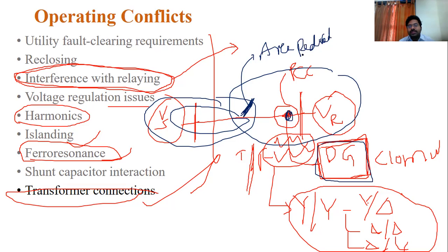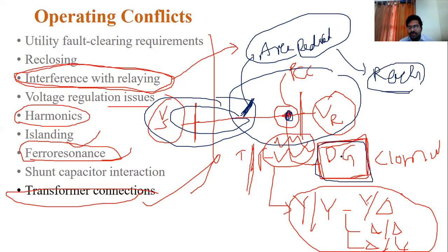Then you call the reduction in that area the reach. Reach of the relay is reduced because of adding this relay to this one. Okay, so if there is any problem occurred in this area, this may directly impact the systems.